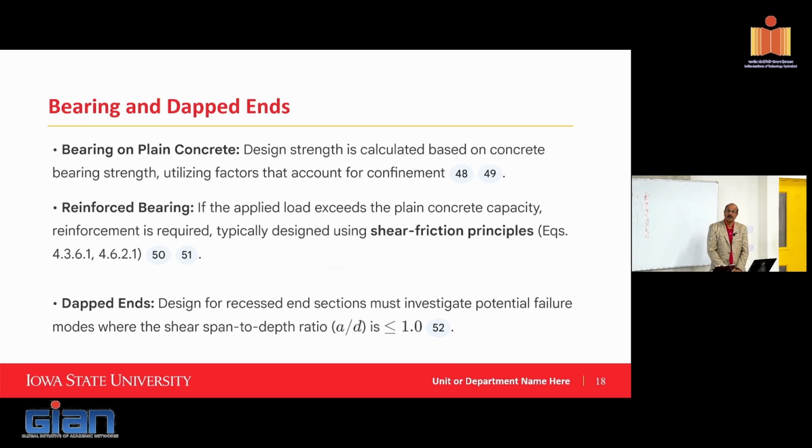If the contact is going to put much larger stresses locally, if you think of a beam supporting at the edges of an inverted T or an L beam, then if you expect larger stresses to be generated, even if you put bearing pads, it will be required that you strengthen that region by basically confining and increasing the strength locally. So that will be the other requirement that they will put in. The DAP 10 design is pretty detailed.